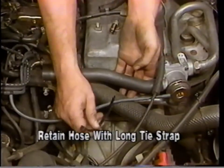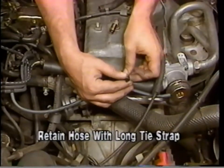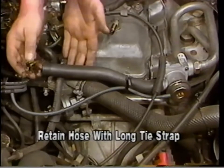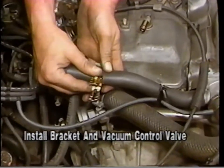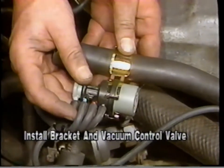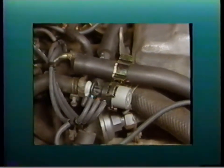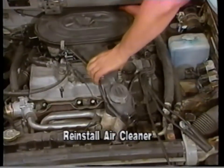Retain the hose in place using the longer of the two supplied tie straps from the parts package as shown here. Next, install the supplied bracket on the secondary air hose near the air cleaner assembly and clip the vacuum control valve into the bracket. Now reinstall the air cleaner assembly.